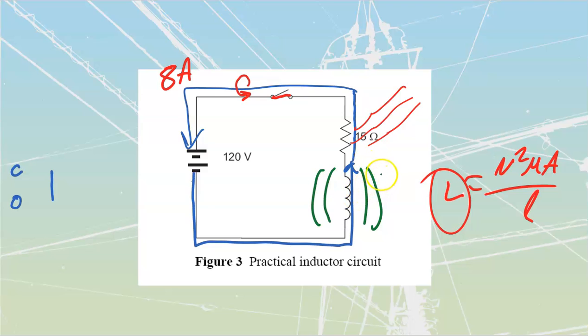When it's stored like this, it's not going to dissipate anything. It just sits stretched out around the outside, and we wait for something to happen inside of this circuit. We can quantify the total amount of energy that we are going to have inside of here. There's a formula for it. It's on your ITA worksheet, but it says that W is equal to 0.5 L times I squared. In other words, the amount of energy that is going to be stored, and this is energy in joules, even though it shows as being watts over here, is equal to half of my inductance multiplied by the maximum, or peak current that I'm going to have flowing through this inductor. That's going to be my steady state current for any one of these.